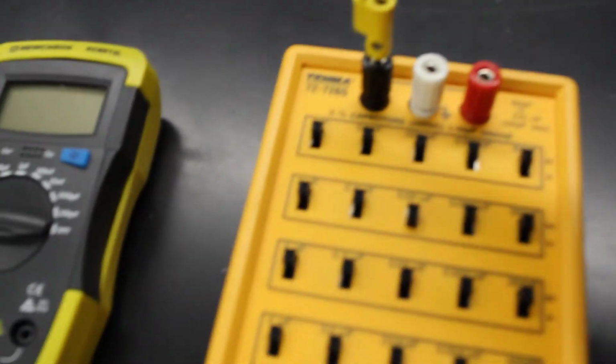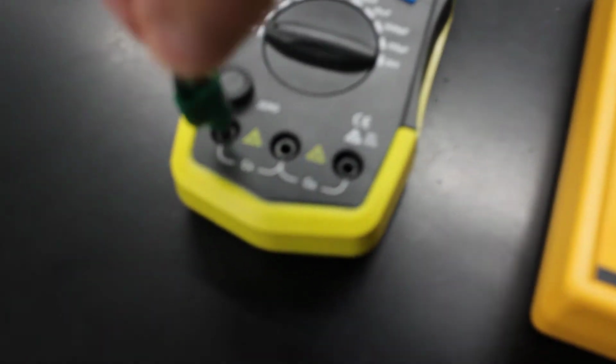Let's do that. So now I'm going to measure the capacitance of the capacitor using the capacitance meter. You just plug the capacitor into the meter directly. Find a setting that gives you the most sig figs. That's overloaded. That gives me 3 sig figs. That gives me 4 sig figs. It's 19.5857 or 58 nanofarads, which is 0.01958 microfarads. So that's what I wanted it to be. And when you see the data sheet, that capacitance will be labeled on there.